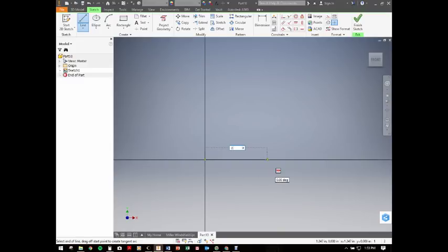at 3.04 inches. You'll note in here where it says 3.040, I don't need to put the extra zeros in there. Autodesk will automatically fill in those zeros. If it's 1.000, all I need to do is type in the number 1.